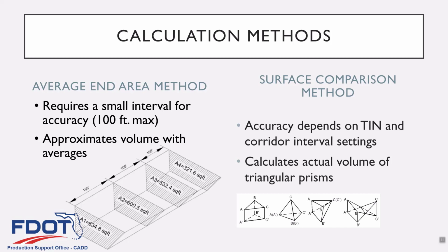So anywhere you can focus in, hey, throw a key station down, clean up those glitches, and it'll provide a better picture and more accurate quantities for earthwork and your other quantities as well that we're pulling off of here, but we're mostly concerned with earthwork. So with that, let's go on to the exercises.